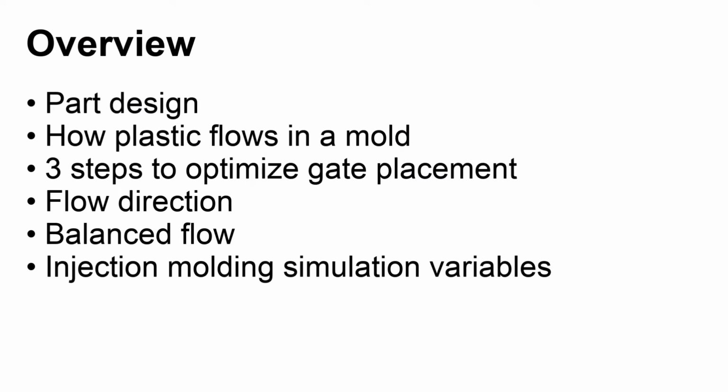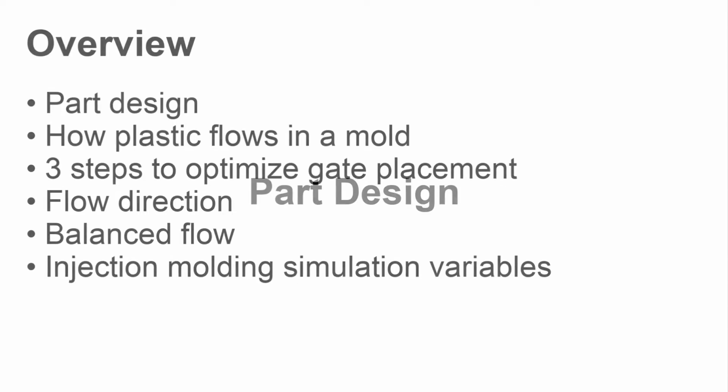We discuss part design in the injection molding process, explain how plastic flows in a mold, identify the steps to take to optimize gate placement, explain what it means to limit changes in flow direction, introduce you to the idea of balanced fill pattern, and show you which process conditions you can change to optimize the analysis.